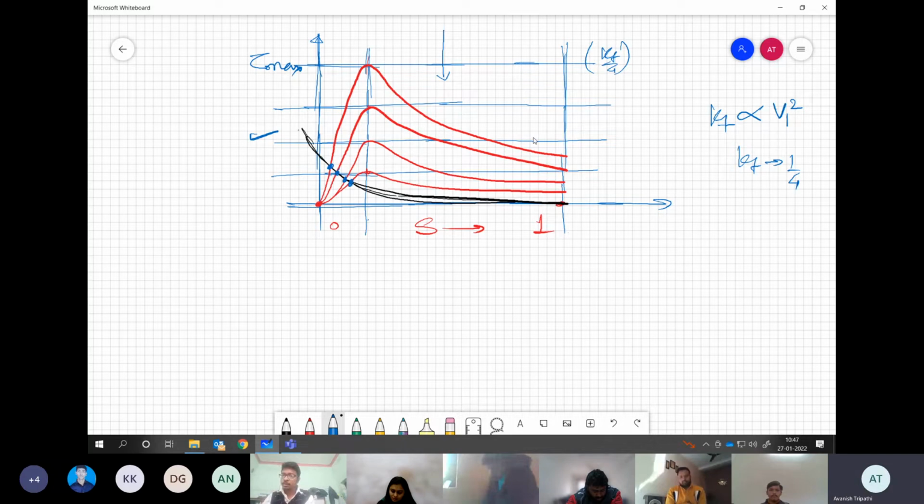So a squirrel cage induction motor can also take advantage of this method. But given that, the load torque at starting should be very, very small, where we are talking about the fan load. It may not be zero, it could be some non-zero value as well. But still it should be lower than the starting torque corresponding to the voltage you are providing. Understanding my point?